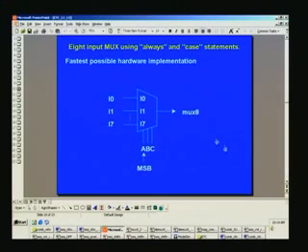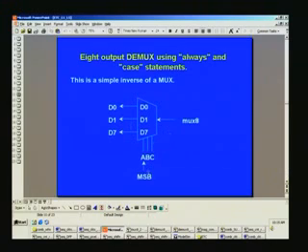And the same demux in the PowerPoint is pictorially depicted here. This is the mux 8 output connected. Note that ABC is the same select pin for the demux here, and A is the MSB, and mux 8 is the input here, and out comes D0 through D7, and D0 is the very same as I0 and so on right up to I7. And the waveform for this one has been obtained from ModelSim, and because it was not visible when we did it in real time, I have made it in Paint Shop, and that magnification is far better, the resolution is better on a TV monitor. That's why it has been done.